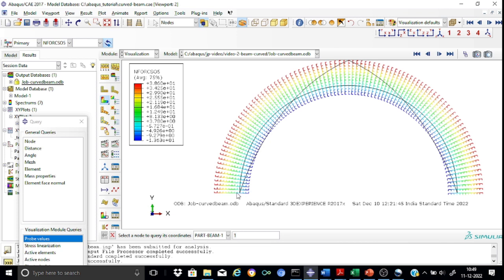As expected, the bending moment should be zero at the pin ends. At these two ends it should be zero, and at the intermediate support it should be maximum. That's a negative moment. In the shear force diagram, we have seen the crossing where the shear force V equals zero. It's somewhere here, and accordingly the shear force being zero corresponds to the maximum bending moment. So this is the location of the maximum positive bending moment, and in the interior support we have the maximum negative bending moment. And now we can just see the values.